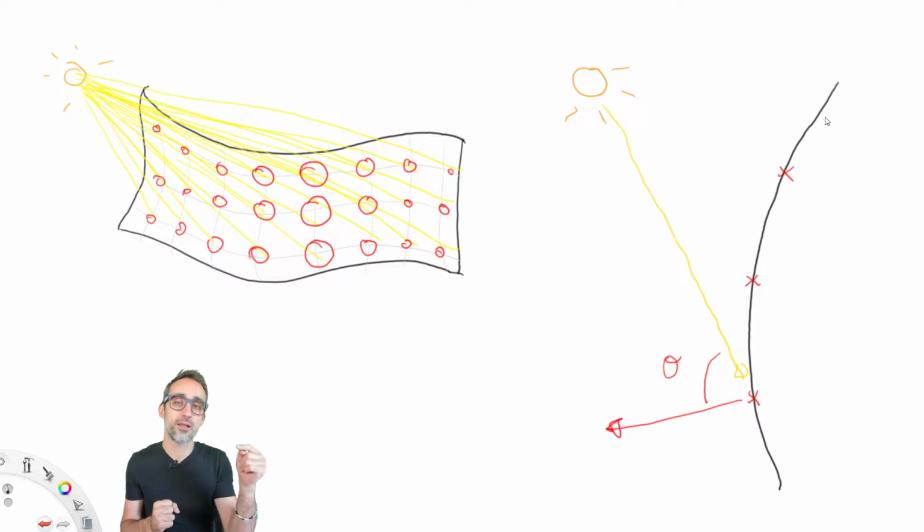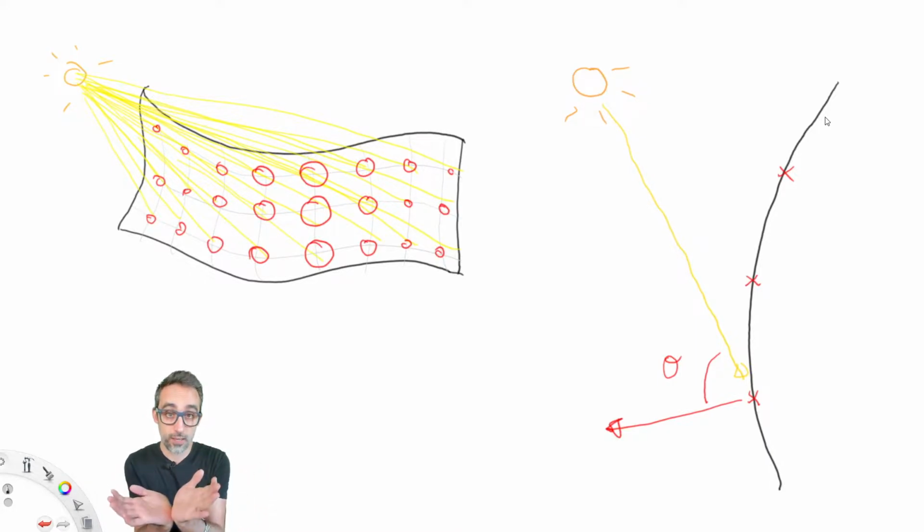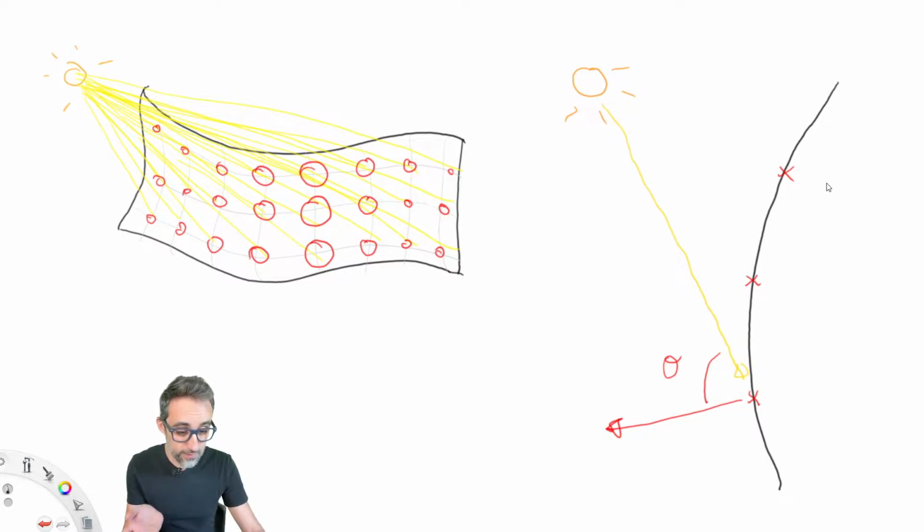And then we're going to calculate the angle between the ray of the sun into that particular point, and the normal, the perpendicular vector from that surface at that point. And it turns out that if that angle is very wide, then the solar incidence of the facade will be very small. And then that opening will be able to be rather large.